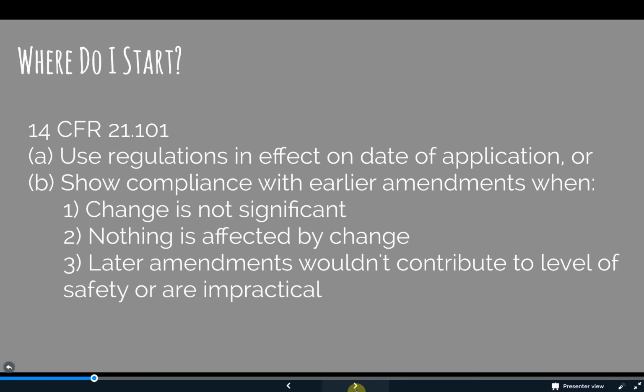Or we decide to add composite wings to an aluminum fuselage. 2. The assumptions used for certification of the product are changed and do not remain valid. Maybe the original aircraft assumed a certain operation, like being a passenger airline, and was later turned into a fire bomber, significantly different flight parameters.